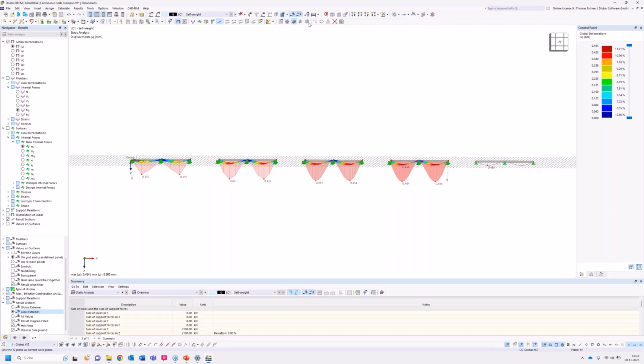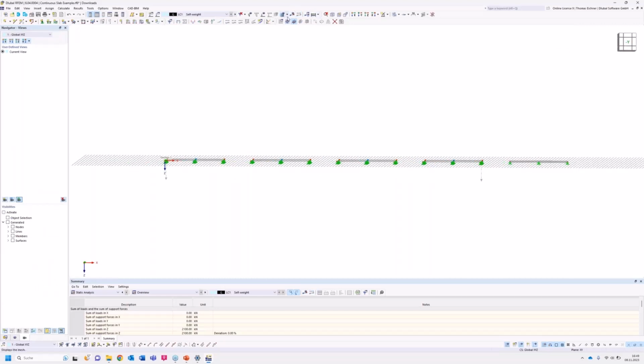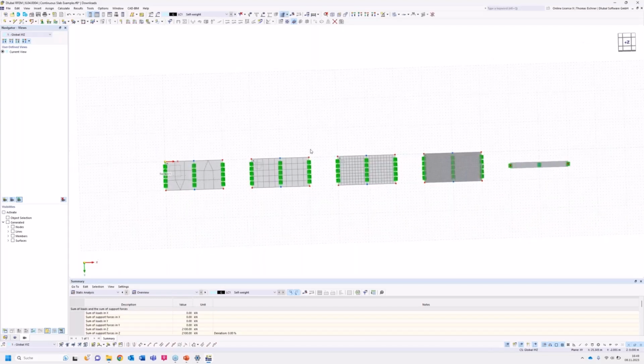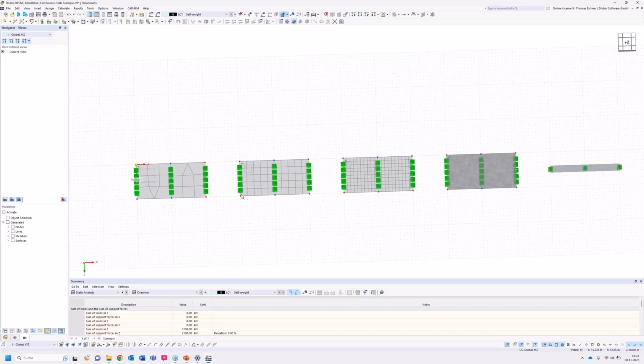And that leads to my rule of thumb for the use of mesh size, which I learned in my studies. So I'm going to show the mesh again. We have like 5 elements right here, and here we have quite more, and way more. The rule of thumb I learned was 6 elements per length. So there needs to be 6 elements in the region we want to inspect.